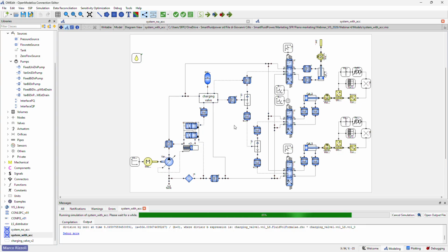The cycle we are analyzing is the same as the previous, since we need to compare the same cycle load. We cannot change, or we would evaluate different things. And also one more thing, I did not show you the specifics of the oil, but it is an ISO VG 46, I think at 40 degrees, so almost cold oil in this case. And we can wait a bit until it finishes the evaluation.